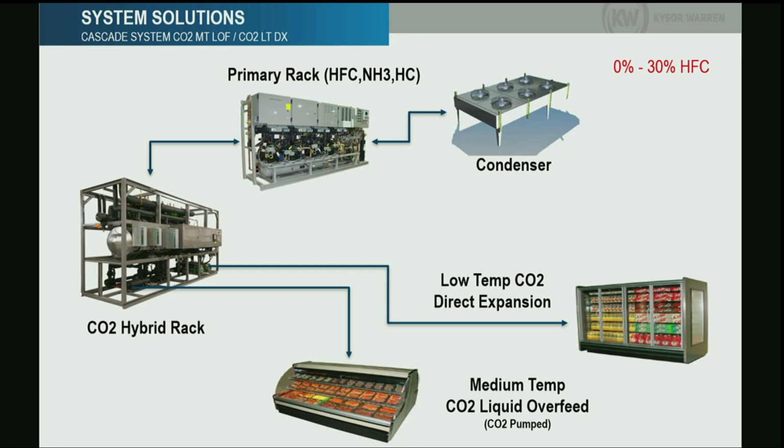Actually, if you have more than one refrigerant, you will have a cascade system. Okay, so it doesn't matter if it's a compressor or a pump, it's a cascade. Yes. Got it. Like the glycol system, we consider secondary systems. In the end, it's a cascade system because you have the HFC chilling the glycol chilling the display cases. It's a cascade system. Yeah. So you have this option that we did in some stores.